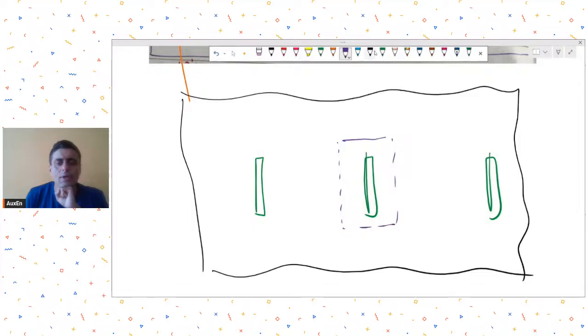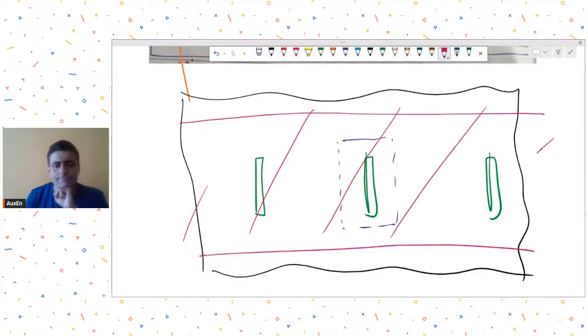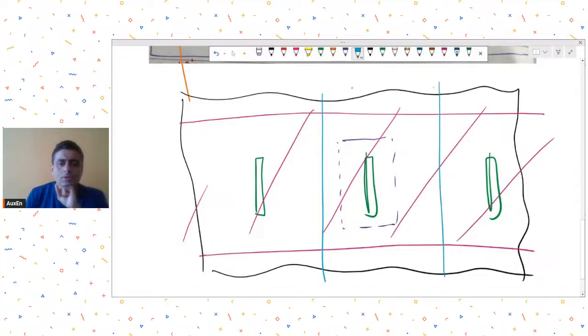Now if you want to have the unbalanced moments, one of the ways can be that you make a strip. So this is the strip in this direction, and then you make another design strip. So this design strip is in this direction. Let's name it as design strip 2, and let us name this one as design strip 1.